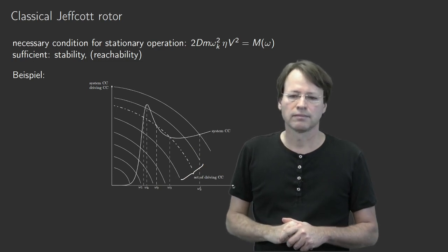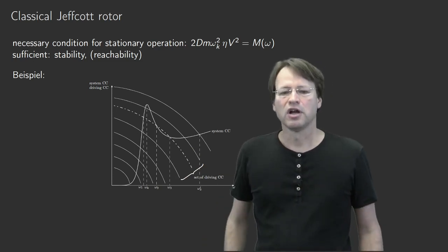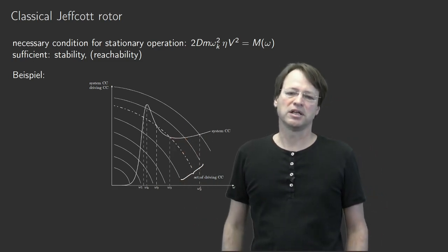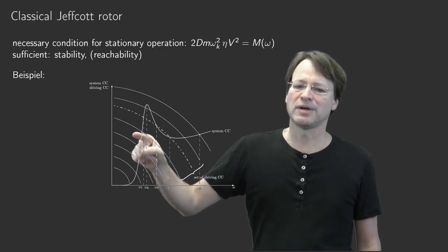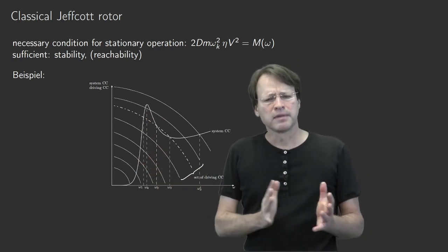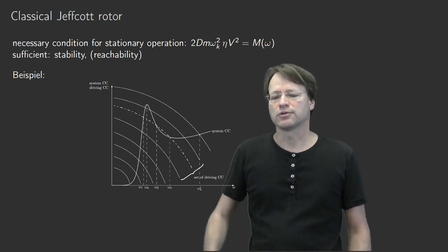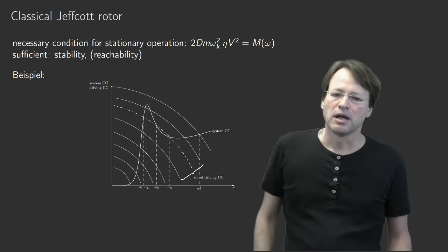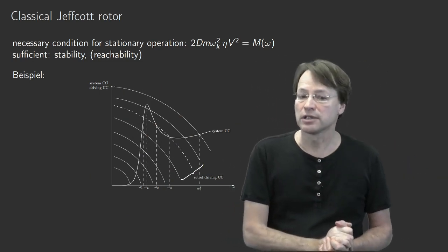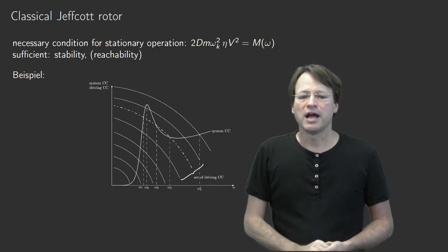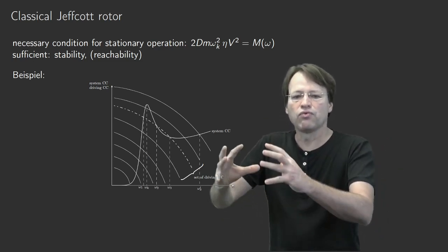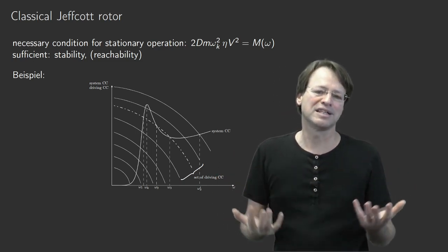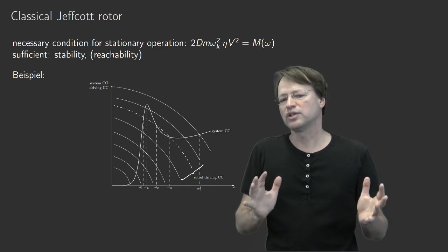I personally would rather like to approach the third one, the third state. Why? Because the first one is quite close to resonance, right? And I don't want to get stuck in that resonance. I would like to go beyond the critical speed, because I know then there is this nice self-centering effect we learned before. And the center of gravity moves into the origin of that coordinate system, and the motion becomes quite calm, quite nice. And we have all these nice properties.